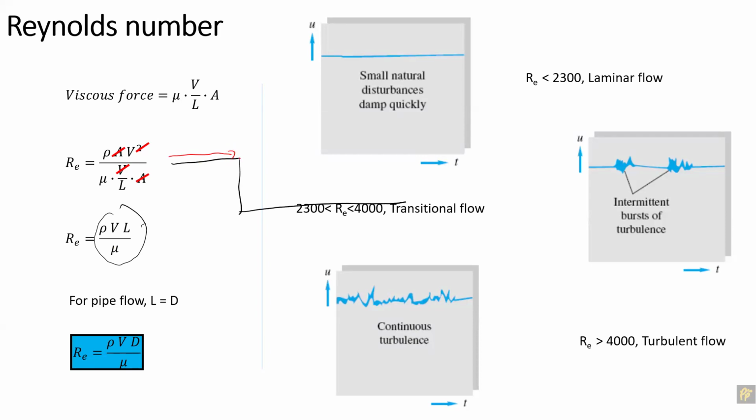So as soon as it approaches here, this will separate from here, and it might attach over this point. This is like a separation location, and this is the reattachment location of that flow. But now if you decrease the height, let's say to this level, for the same flow, the attachment point will be different. So this might attach over here.